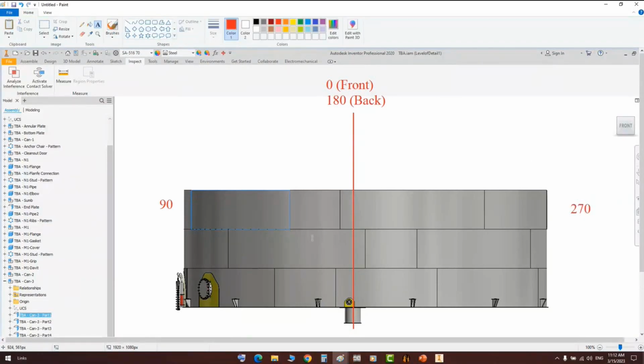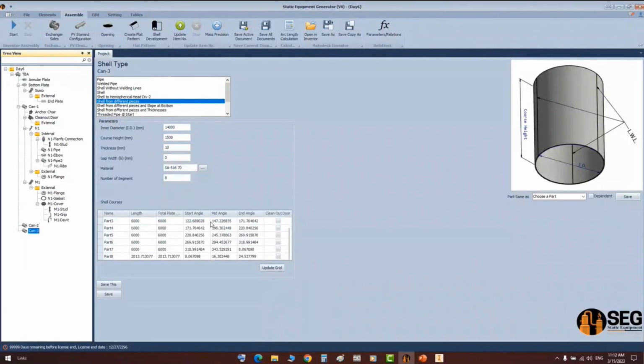Now, if you take a look, we define that we need the longitudinal welding line orientation of this one, which is that one. Okay, the first longitudinal welding line will be located with 3 meters offset. If we come back here, we calculate the angle, which is that angle, which will give us 3 meter offset from the 0 degree.